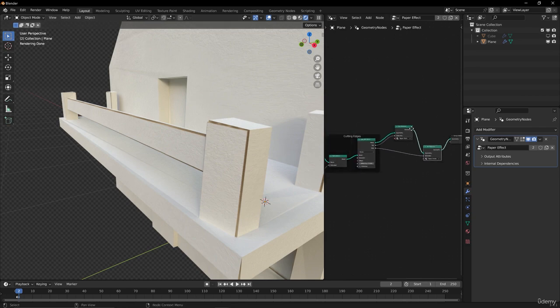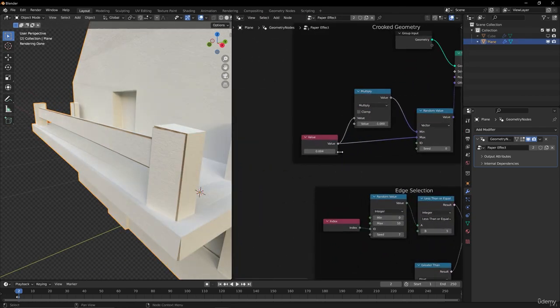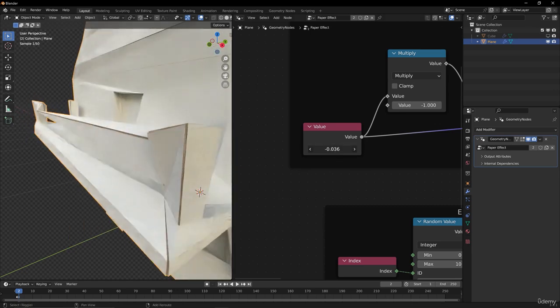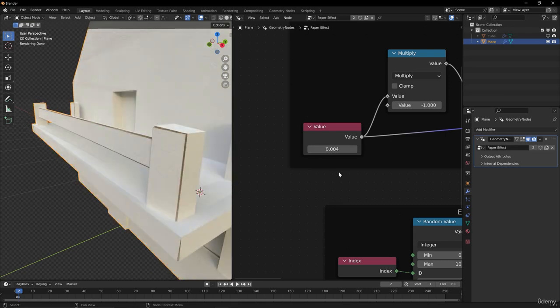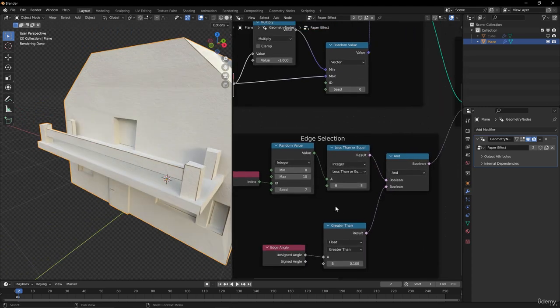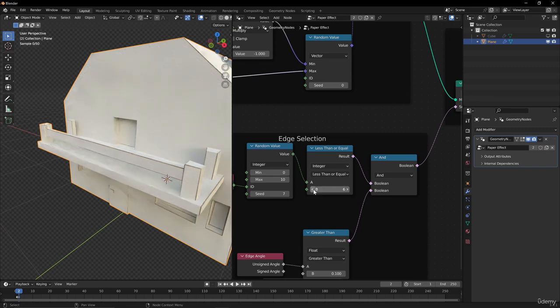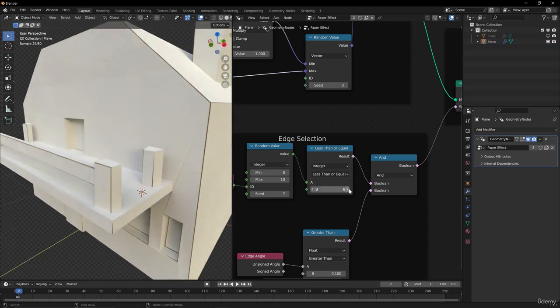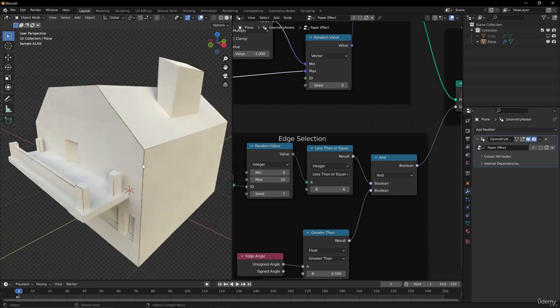So this has a pretty sympathetic look and is very quickly editable. Yeah, so you can either create or edit the tree here, for example, increase the crooked points here and increase this. I mean, of course, it's very hard here, but you can see that you can decide how deformed everything is. Or when you want to reduce it a bit, you just make this 0.003, and then it's a bit more straight. Or if you want to increase the amount of edges which are cut, then you can just increase this or decrease it to make less cuts. Yeah, for example, it depends on which object, of course, you're operating with. But here in this case, I would say a bit more is maybe better, like this. And then it looks a bit more realistic.